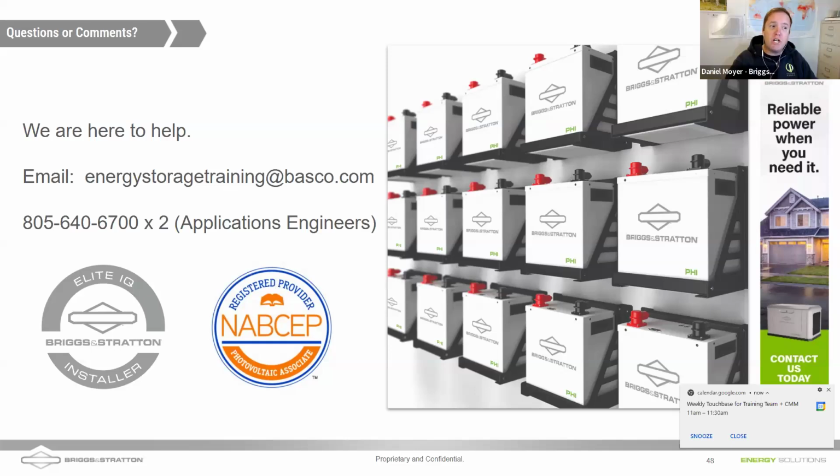Great. Which Briggs & Stratton generator will be able to max out a 19.2 kilowatt terminal? Again, you can certainly install different sized generators. I don't think we make the 20K anymore, and I believe it's the 22K. You would be able to supply that full 80 amps continuous max through the Solark 80 amp generator port. And of course, Andy Renner, any of the generators you could max out on the utility port. Andy's mentioned it's a 100 amp breaker on that 22 kilowatt.